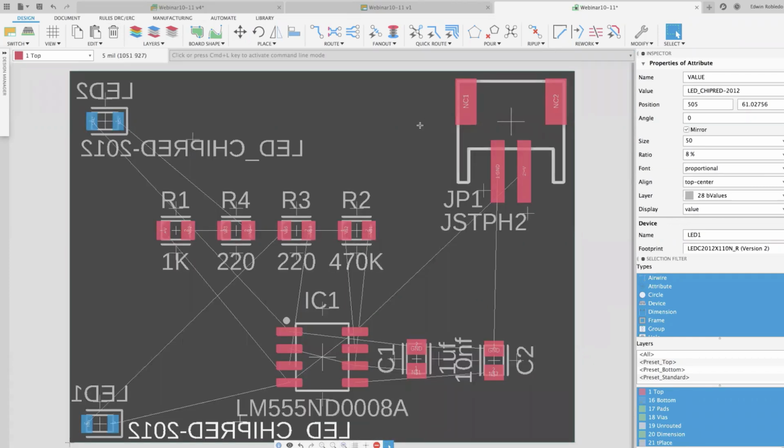We've got it going. Now, the routing tools are located right here. These are the first ones I'm going to start with. There are some more, but I'm going to start with this one right here, the manual route command. Now, I have to admit that it's common for you to manually route your board. You really want to try your best to stay away from the auto router.